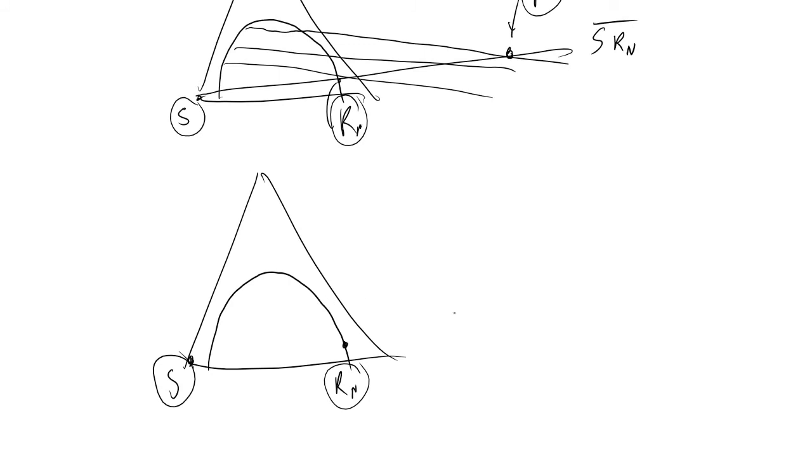We will have our pivot point out here. And we will know a priori what our top tray composition will be. It will be E1. And sometimes with these ternary diagrams there will be a bit of interpolation involved with the tie lines.